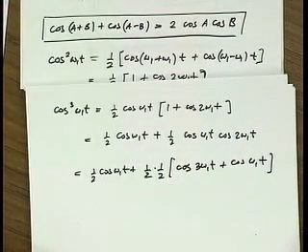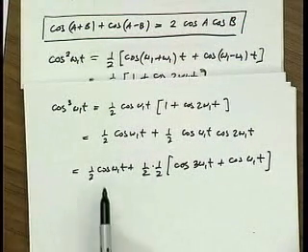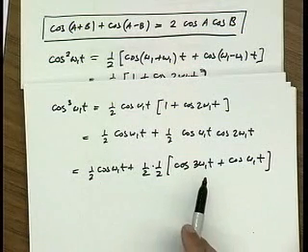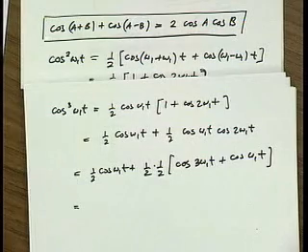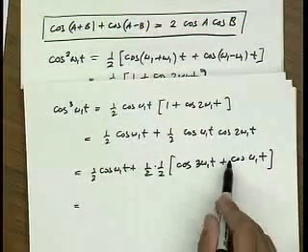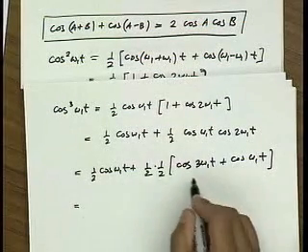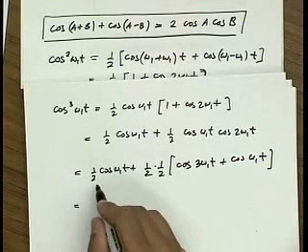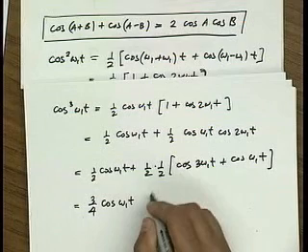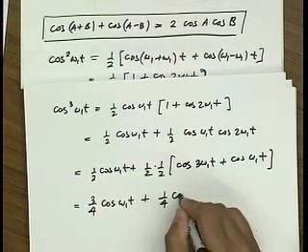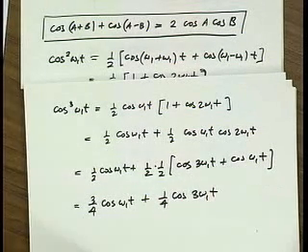So we see that the cubic generated fundamental and third harmonic. That, of course, matches the results we did last time when we did the binomial expansion. If I sum here, I get 1/4 plus 1/2, or 3/4 cosine omega 1t plus 1/4 cosine 3 omega 1t.